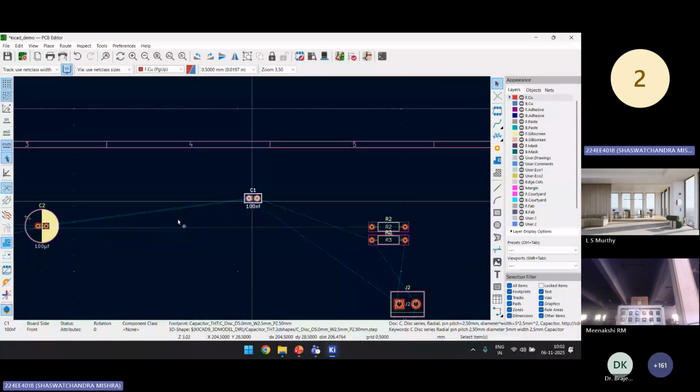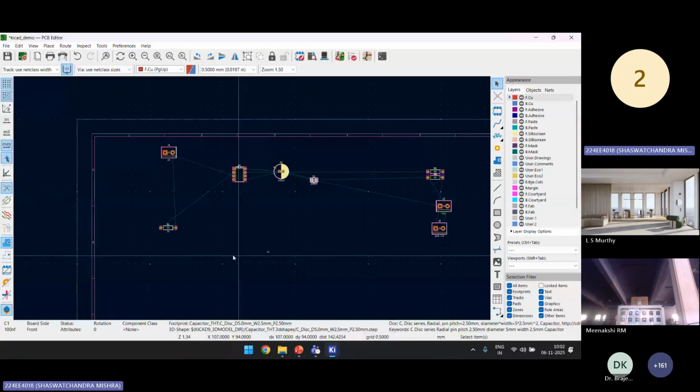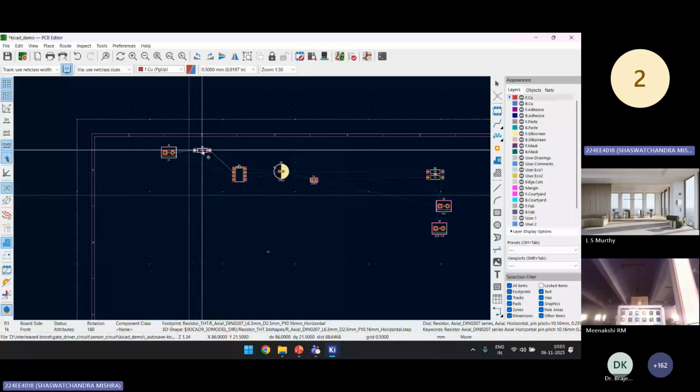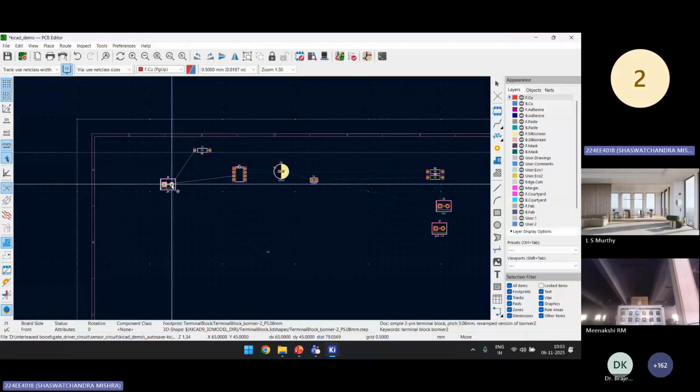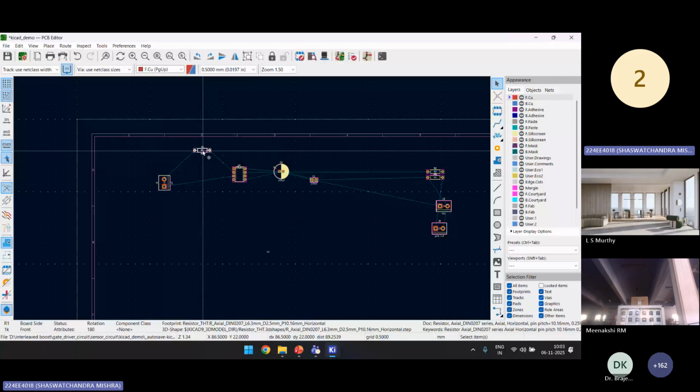So this portion of circuit design entirely depends on you, how you can optimize the placement of components and how you can minimize the required area. Here you can click on each symbol and press R to rotate them. I will be placing it here like this. The closer the better, because we want to minimize the area and make the circuit more compact, right? So I will be placing them like this.